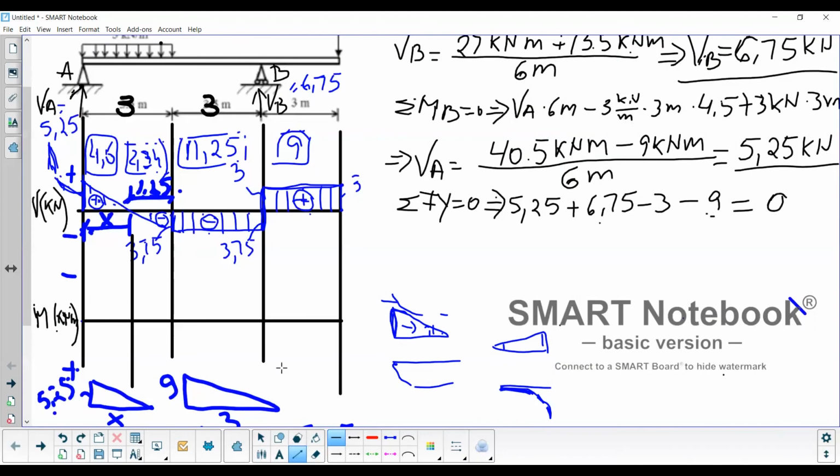So let's try and do that. In my case, I'm going fast and then slow. So starting at this point, I'm going to go towards the positive side of the moment diagram, and the value here is going to be 4.6. Okay, I'm going to make it bigger like this. So I'm going to go fast and then slow. And this is on the positive side, because my shear diagram here is positive.